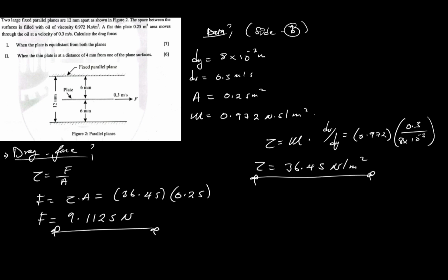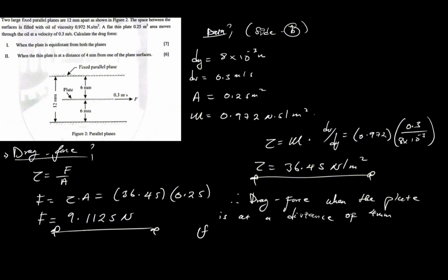So moving on to the final aspect. Now, to conclude this, what you have to remember is that we will say therefore the drag force, when the plate, excuse my handwriting, is at a distance of 4 millimeters from one of the plane surfaces, will now be the effective drag force, which is going to be 9.1125, which is the drag force in section B, summed up with the drag force in section A, which was found to be